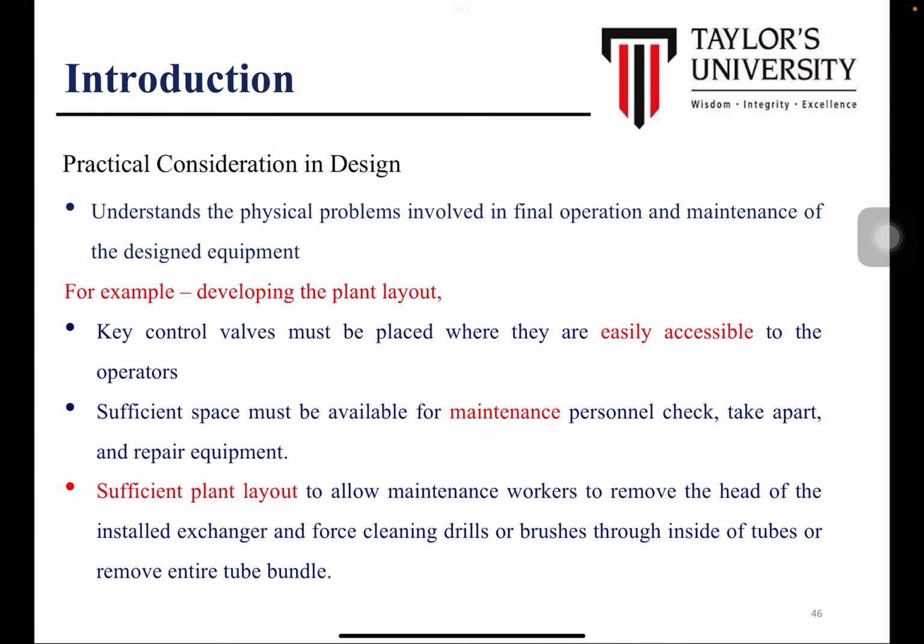The layout must allow maintenance workers to remove the head of the installed exchanger and force cleaning drills or brushes through the inside of tubes, or remove the entire tube bundle. The heat exchangers are very huge. If you want to remove the tube bundle from the heat exchanger, you need a certain space to remove it out, right? So make sure all these things are properly planned.